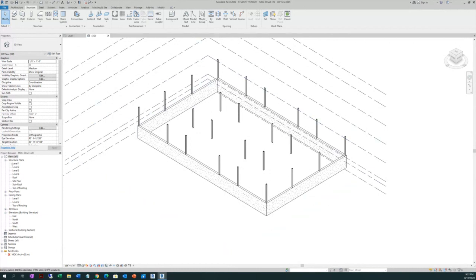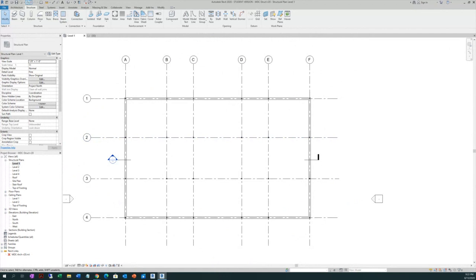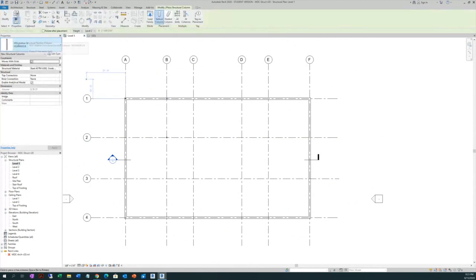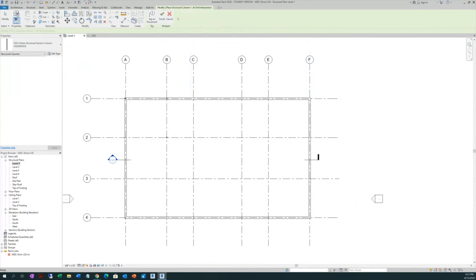Okay, I want you to do it like I did already. I'm going to repeat. You go to structural, you go to column. You have the column there. Make sure it's the hollow structural section. Then immediately you will have something at grids. It's going to look for the intersection of your grids. You click on that. Even though you have placed some columns in advance, it's not going to duplicate them.